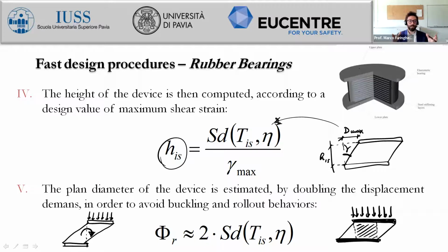So there is automatically a set of internal forces which surely exceed the design limits, maybe also within the reinforced concrete plate. There are bending moments and shears which are highly underestimated, I mean, in the design phase, because the static scheme of the plate has been changed by this situation.